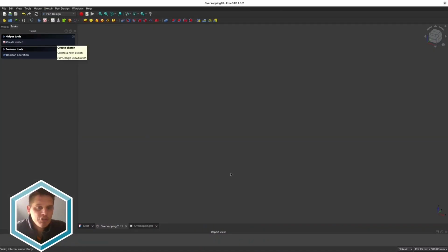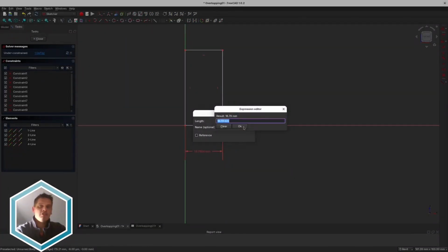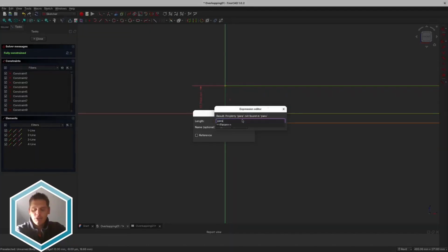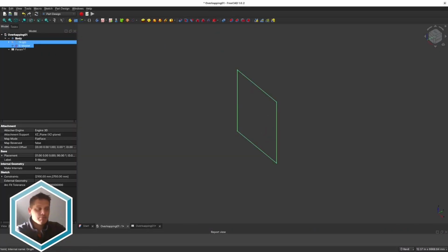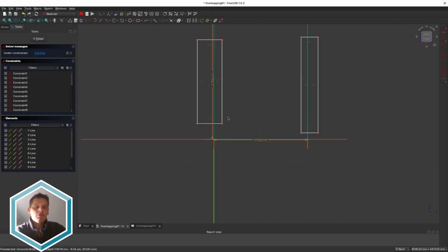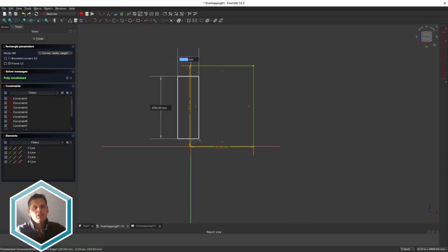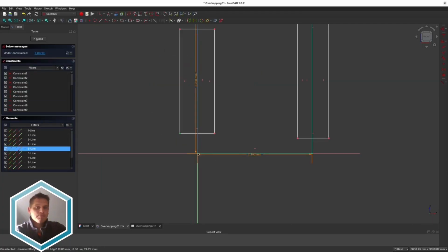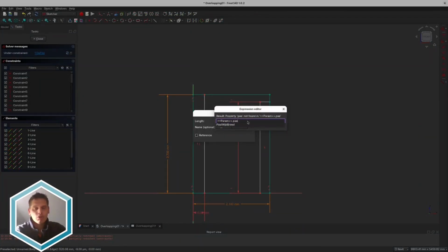First I make a spreadsheet where I put all the main dimensions in, which makes it easier to change afterwards if I want. It could be done a bit simpler by making a VarSet, which is basically a holder of variables, sorry, in the normal tree list. However, I like working with parameters with spreadsheets if it gets a little bit more complicated.